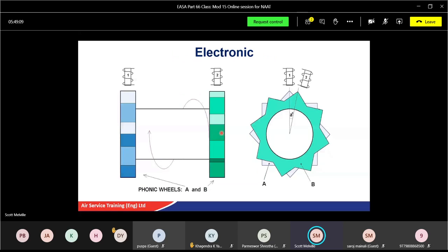Electrical one is pretty much what we saw already between your wheels on the speed. So we're using two sensors. Torque is a twisting moment, isn't it? So we twist something, we're torquing it. So we're having two sensors, A and B, on two intermediate shafts. The more the twisting, or the difference between those two sensors, the greater the torque, and that's produced electronically. So the principle of this one is it measures the deflection, so the gap between sensor 1 and the gap between 2, indicated by this angle here. So the greater the angle, the greater the torque.